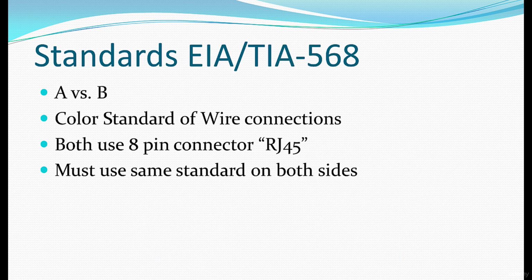Standards are EIA/TIA, which is Electronic Industries Alliance, Telecommunications Industry Association 568. You can also see it as American National Standards Institute, ANSI 568. There is an A and a B, which talks about the color standard of the wire connections. Both use the 8-pin connector called an RJ45, and you must use the same standard on both sides so that you can get a connection.